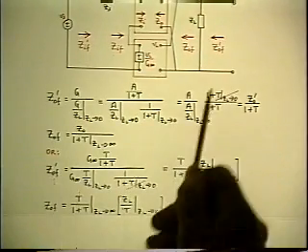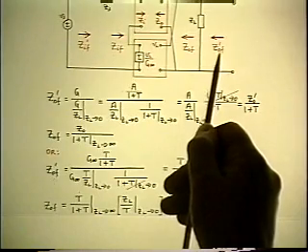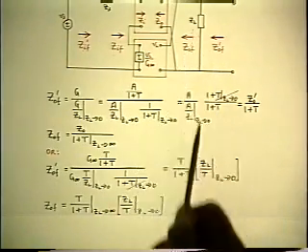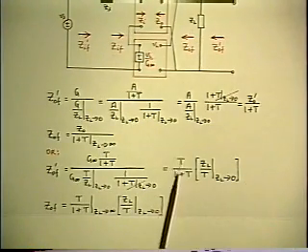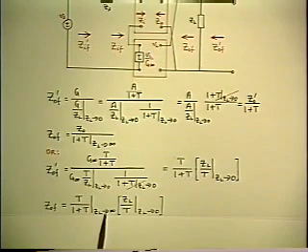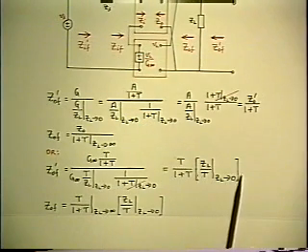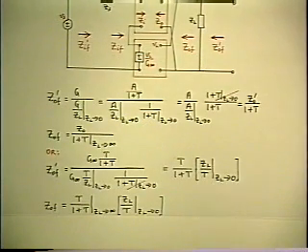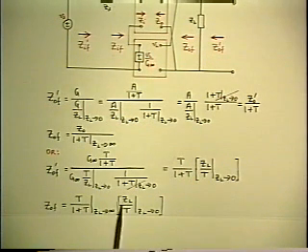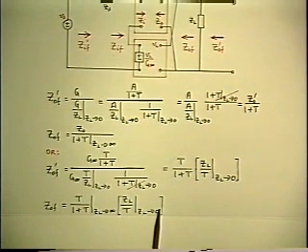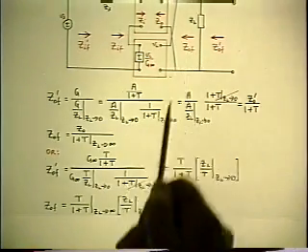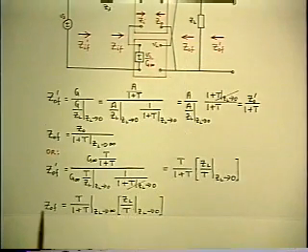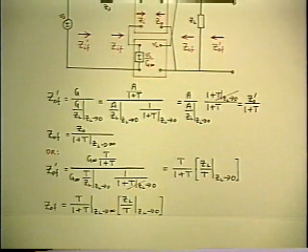So now, having found the outside closed loop output impedance, you can find the inside one by letting ZL go to infinity in the answer. So you write the first term with ZL going to infinity, and when you look at the second term, ZL is already limited out, so it doesn't change when you let ZL go to infinity. So that square bracket remains. So you find that the inside closed loop output impedance is also determined only by T.